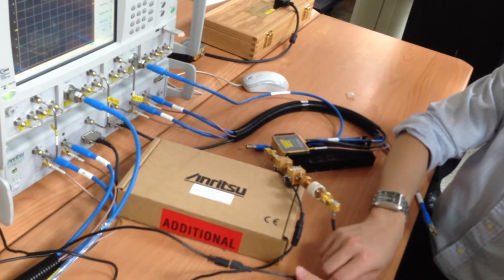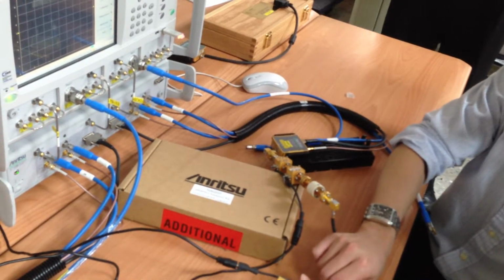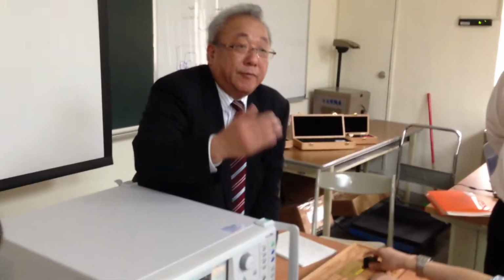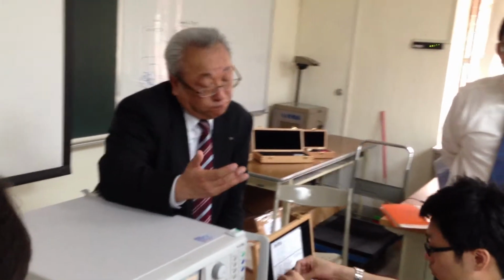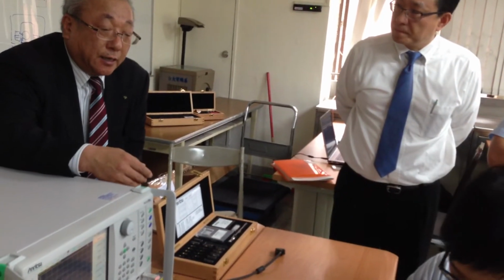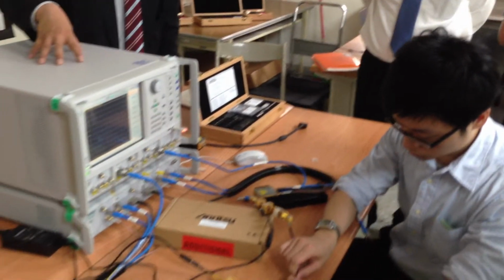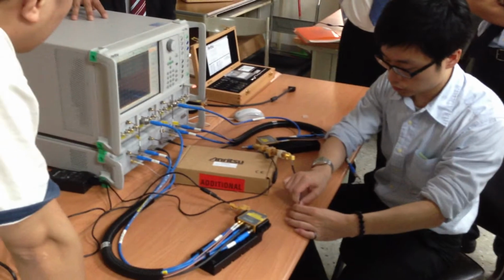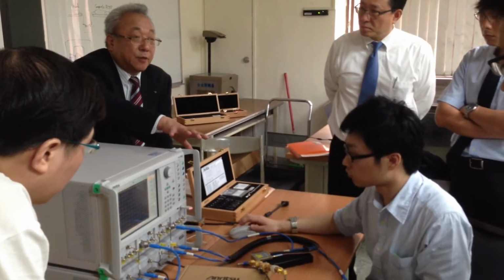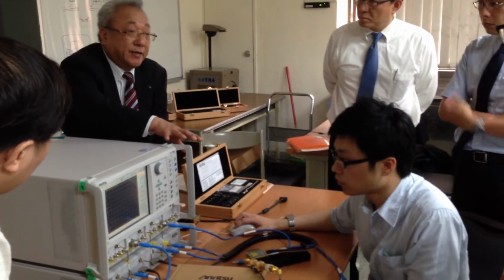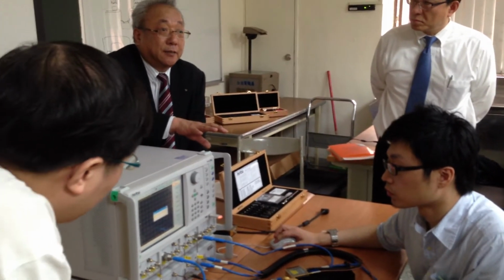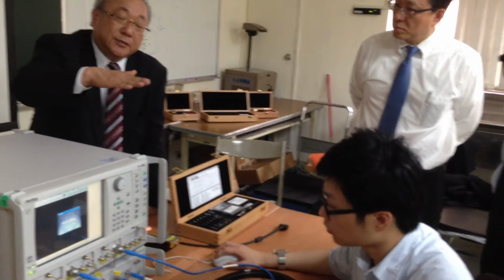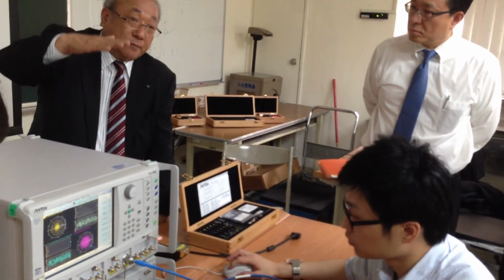No, so this time we already took the DUT S parameter data before, and also we already calibrated the receiver. So we will use this one. It is very insensitive, depending on the composite receiver and the VNA stability. Okay. So they need some warm up time for the VNA, about 1 hour, and for the DUT and this kind of composite receiver, depending on the amplifier, about 10 minutes or something like that. If you measure the noise figure just after turning on the bias, the DUT noise figure may drift a little bit with temperature.